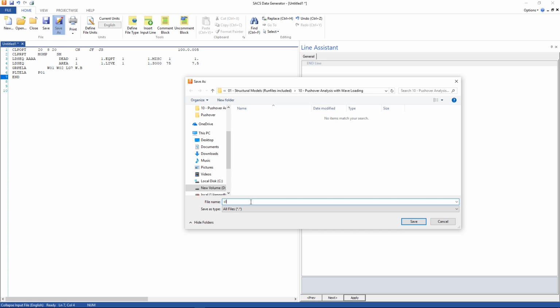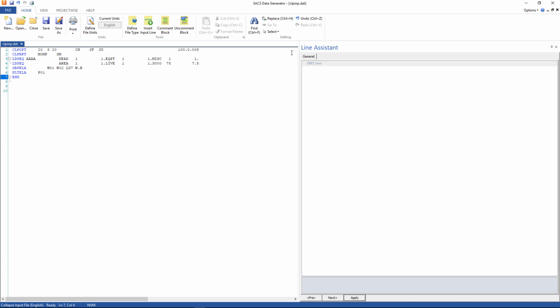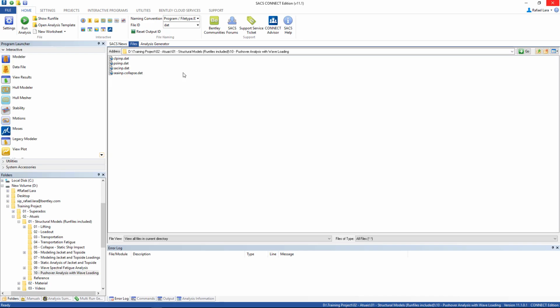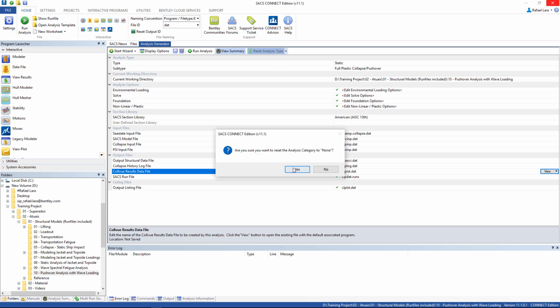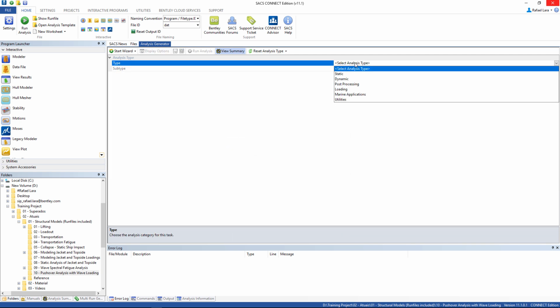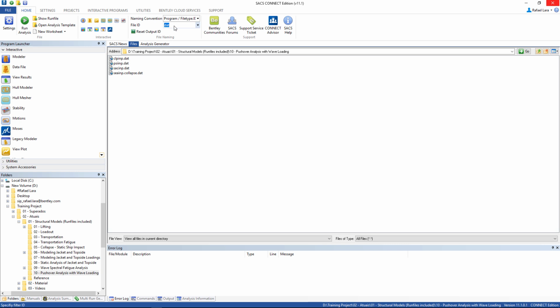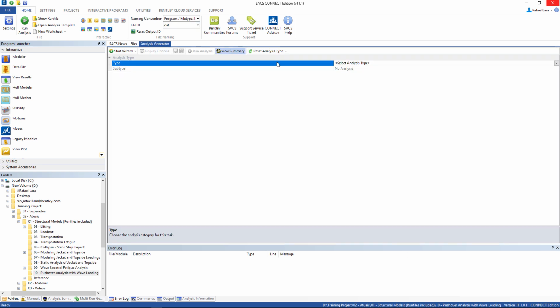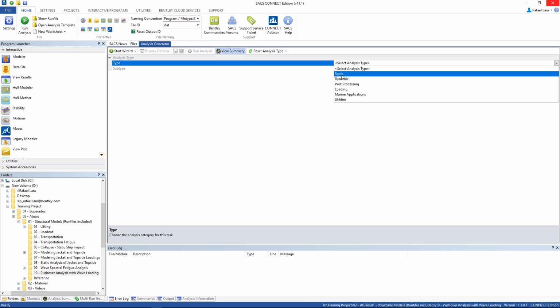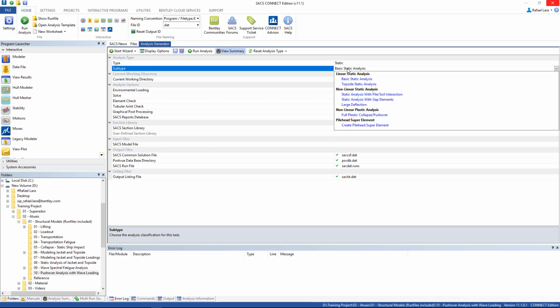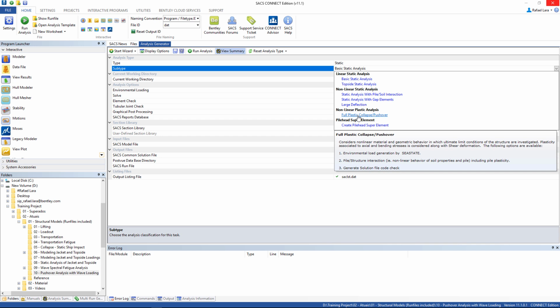The name is clpinp.dat and save. Here it is. Let's go to the analysis generator. Let's select the static, and the subtype is full plastic collapse pushover.